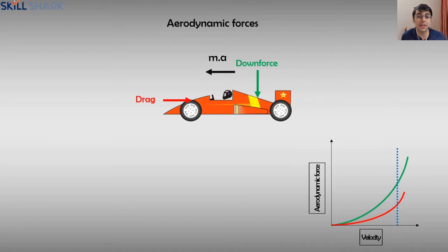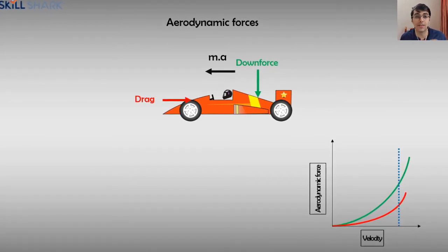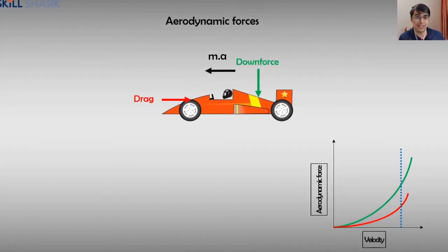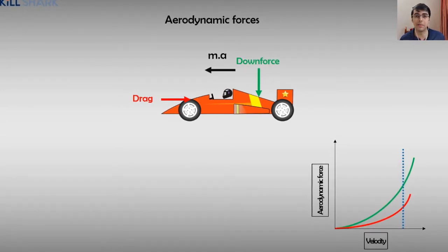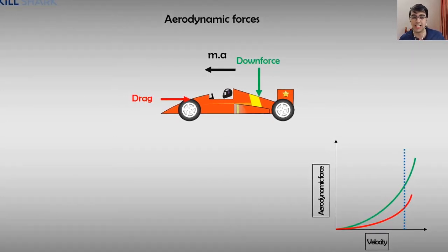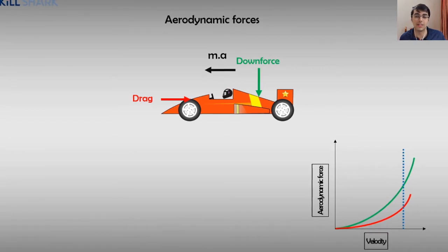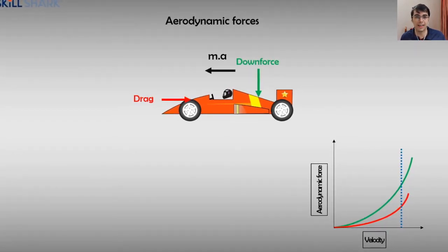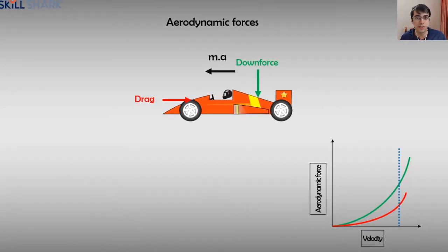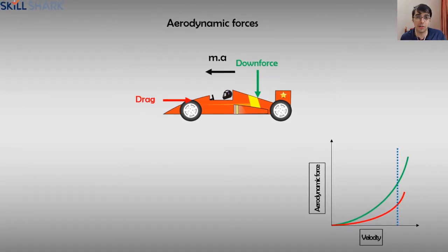Now, the culprit here, of course, is drag. So you want to reduce that drag so that you can increase your terminal velocity. It's always going to be there. You're always going to have a terminal velocity, either because you're limited by the potential of the engine, or you're limited by the drag. But the one thing that you really have control over is reducing that drag. And that is what a large percentage of aerodynamic design is focused on.